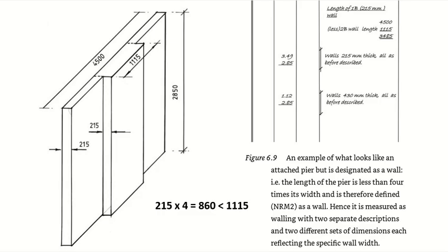So this is one wall and these are two other parts of the wall. The total wall was 4.5. Out of 4.5, I am taking this middle part separately. I calculate it separately. So from the total length, I will subtract this because this is separate. The part of the wall which has the projection will be calculated separately. From the total, I will subtract this much. I will get 3.49.